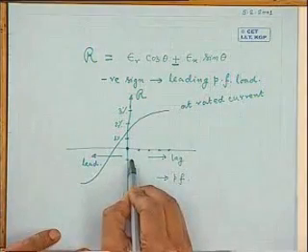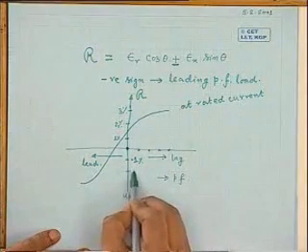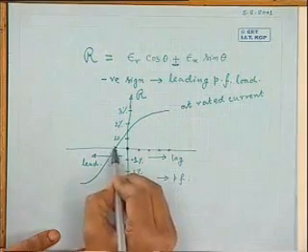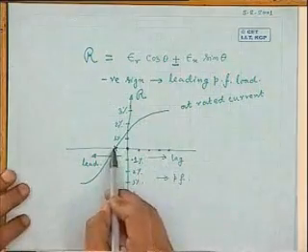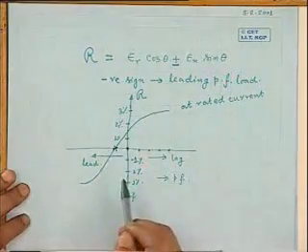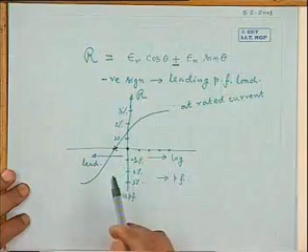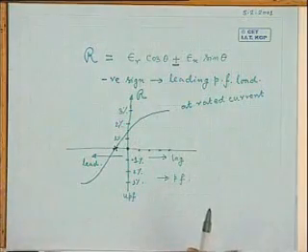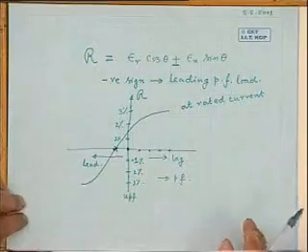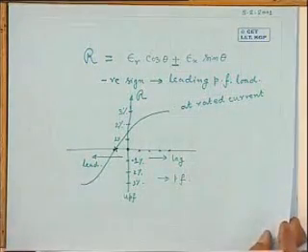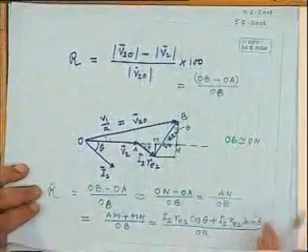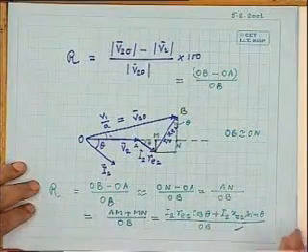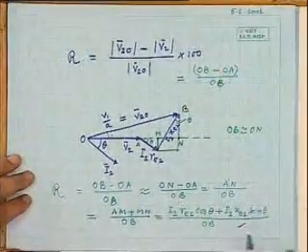You should have that idea. Similarly, this side will be minus 1%, minus 2%, like this. Obviously, regulation will be 0, as you predicted correctly, at some leading power factor of the load. At resistive load also, regulation will be positive. So regulation should be as small as possible in a transformer. Now, sometimes a slightly accurate formula is desired. Of course, in almost all the cases, we will apply this formula quickly.